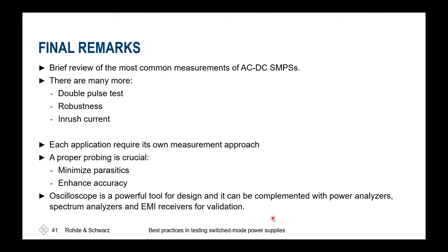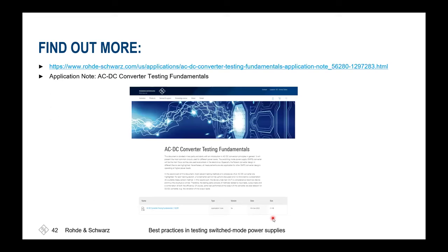Switch on the FFT. It takes about 5 to maybe 10 additional minutes on your setup at your desk, and you immediately see what's happening inside your system, which frequency components occur, and you are already better prepared to see also from which stages in your design these might be occurring if you'd like to hunt down the EMC issues.